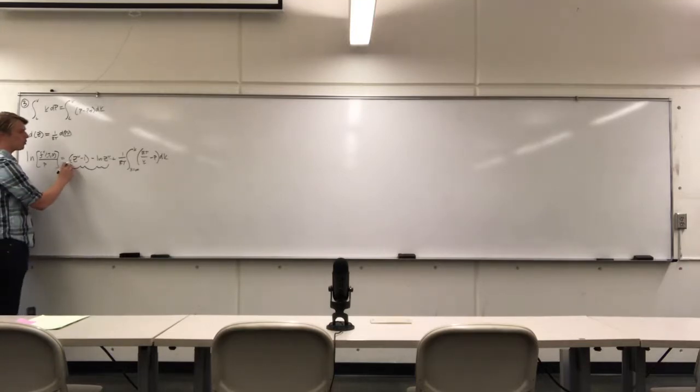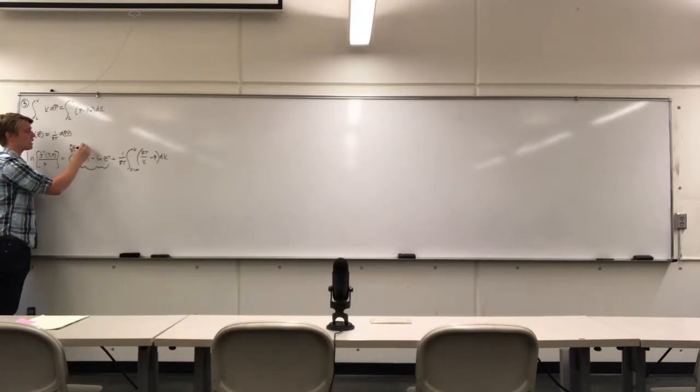So when we go through and we substitute in the compressibility factor, when we see terms here like z of v minus 1, that means this is the PV of the real fluid divided by the RT minus the PV over RT of an ideal gas, which makes it very easy for us to say that's just 1.